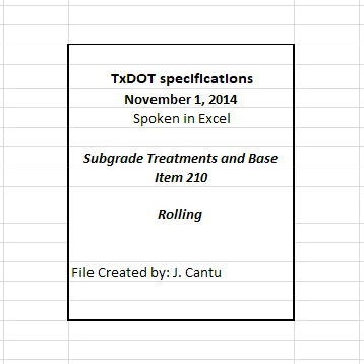Select and maintain the operating load and tire air pressure within the range of the manufacturer's charts or tabulations to attain maximum compaction throughout the lift, as approved. Furnish the manufacturer's chart or tabulations showing the contact areas and contact pressures for the full range of tire inflation pressures and for the full range of loadings for the particular tires furnished. Maintain individual tire inflation pressures within 5 psi of each other. Provide uniform compression under all tires.